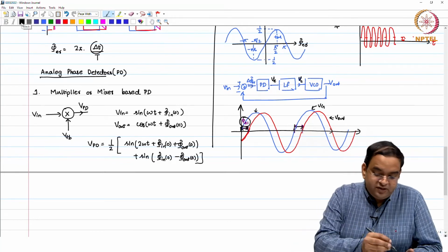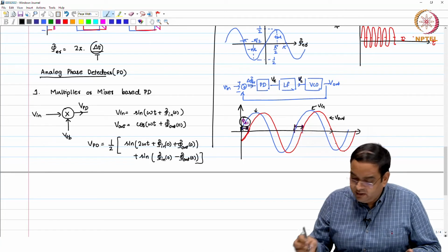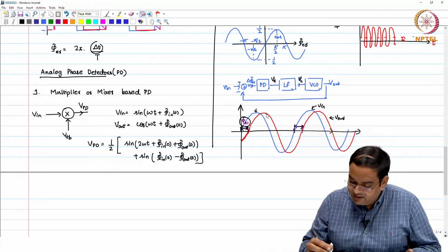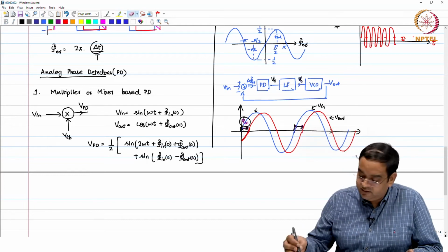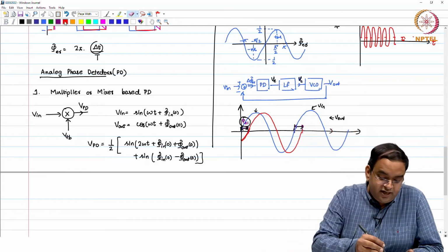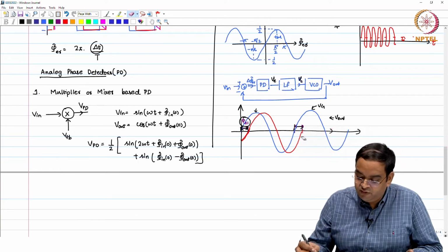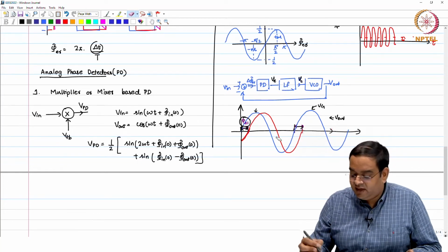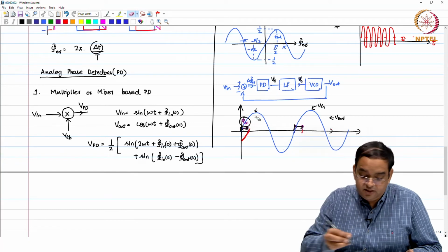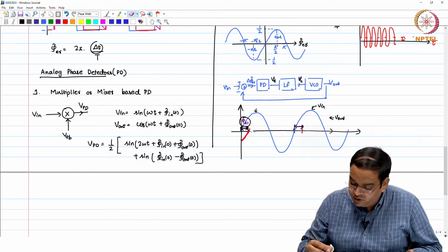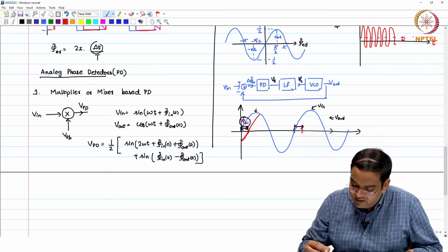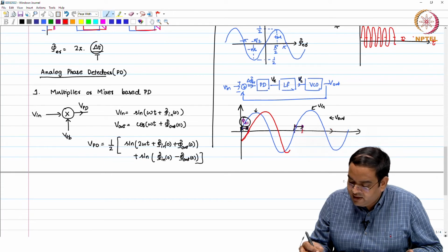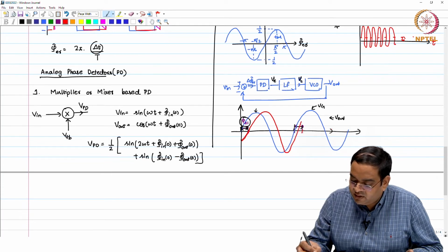The VCO frequency increases. Now, what does it mean? If the VCO frequency increases, and let us say this happens pretty fast, then your next rising edge should ideally come closer, because I increased the VCO frequency.